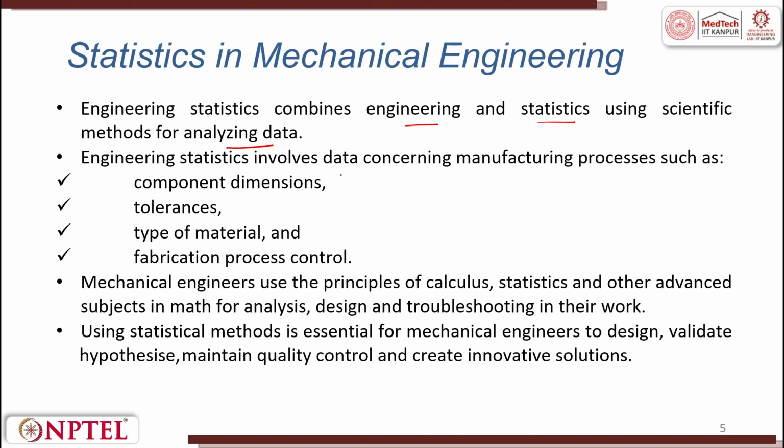Engineering statistics involve data concerning manufacturing processes such as component dimensions. If I am talking about a nozzle to be fit right in a specific slot in the boiler, that nozzle has to have a tolerance equivalent to what the boiler has at this specific hole or specific thread there. Now, we talked about tolerances in the first part of the Basics of Mechanical Engineering course series. Here I am talking about a fit: it could be clearance fit, it could be interference fit, it could be transition fit.